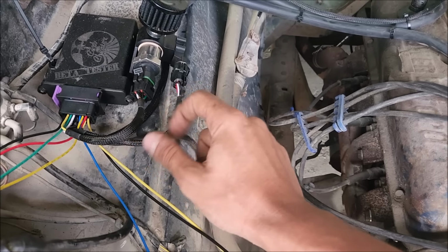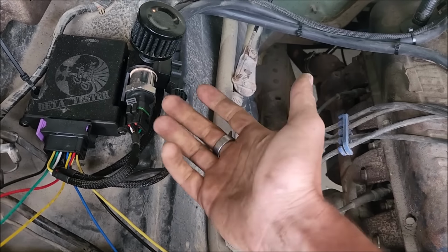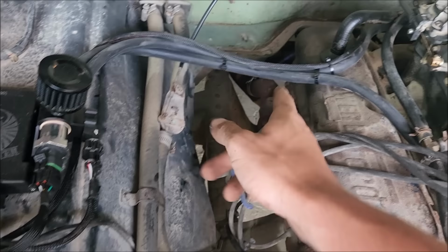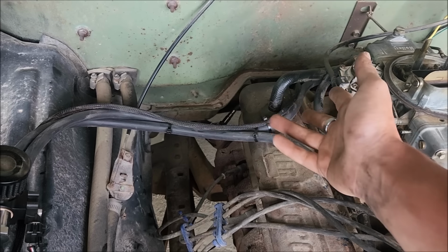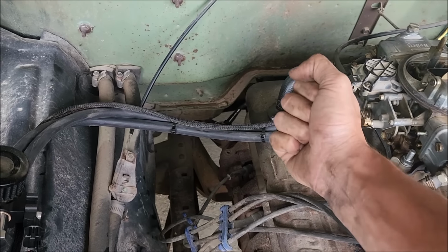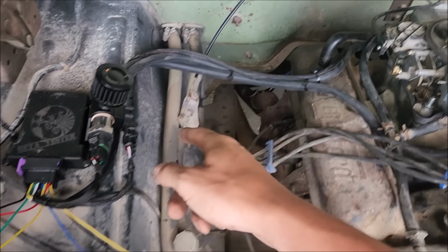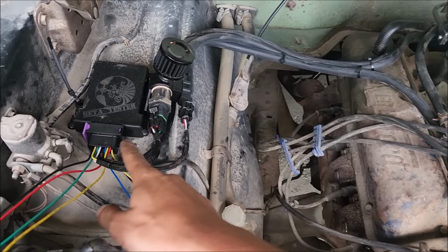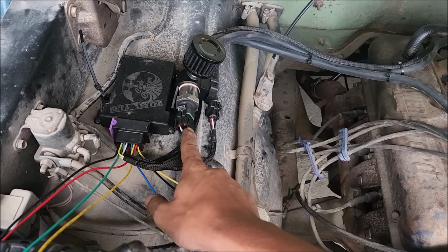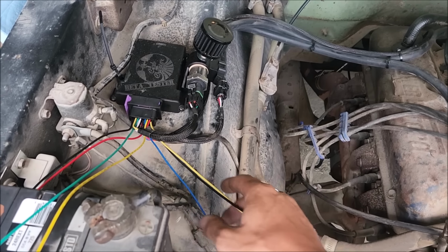Side note on all of these connectors, you want to hear them click in, and you think that that's obvious, but sometimes, like the Bosch widebands, when we use a true Bosch wideband, they really take some force to click in. So you need to make sure you hear the click or else it's going to come unconnected. And don't be surprised if you have to push them with some force the first times. These are all brand new, and so sometimes it takes a little bit more effort than other times. But anyway, they're all clicked in, we're good.